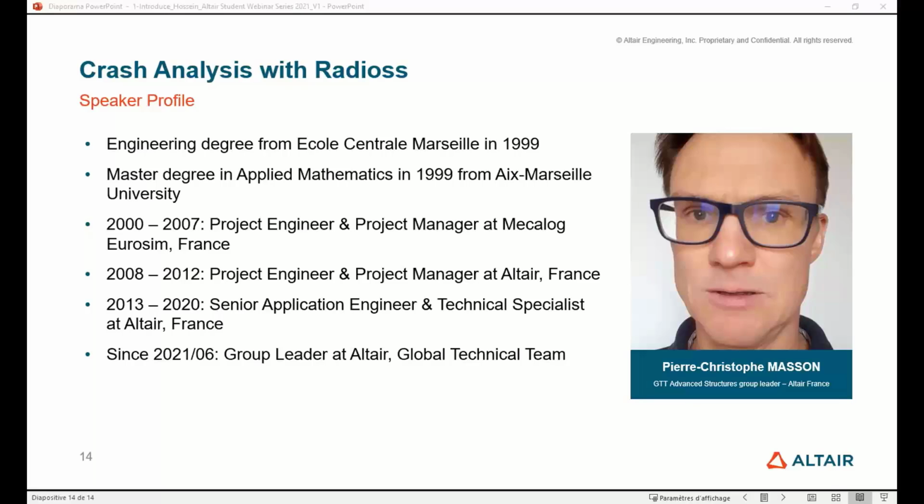Yes, the warnings and the errors reported by HyperWorks might be different from the errors reported by Radioss. If there is an error during Radioss starter, you will not be able to run the engine file afterwards. So these errors are mandatory and need to be corrected.